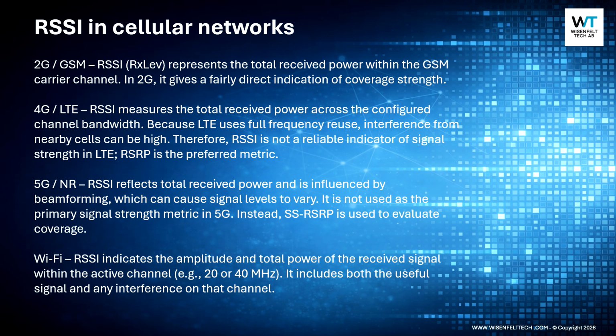In Wi-Fi, RSSI indicates the amplitude and total power of the received signal within the active channel, e.g., 20 or 40 MHz. It includes both the useful signal and any interference on that channel.